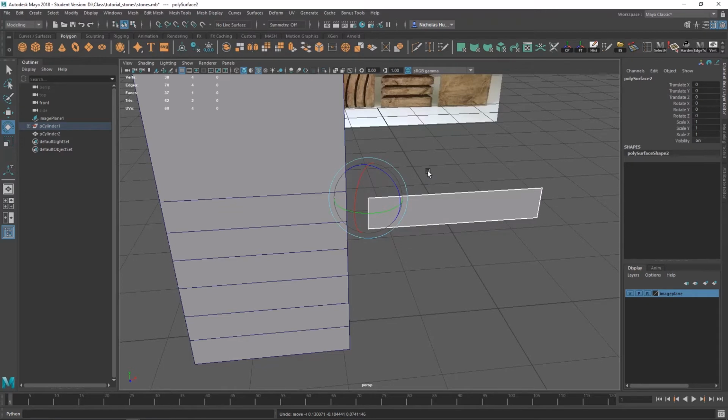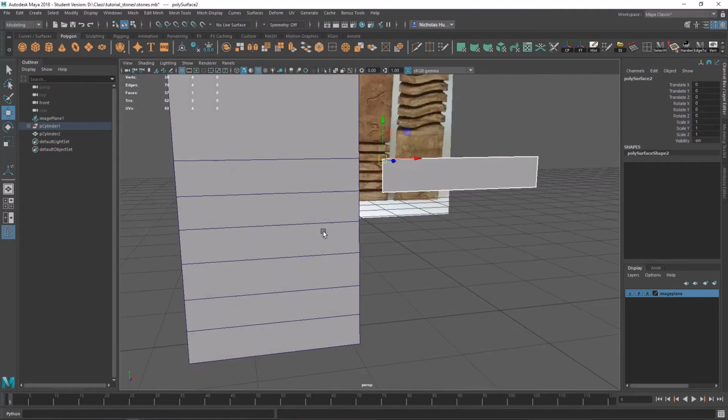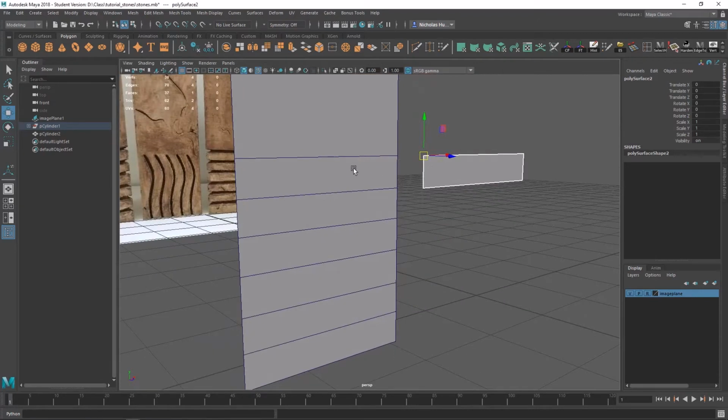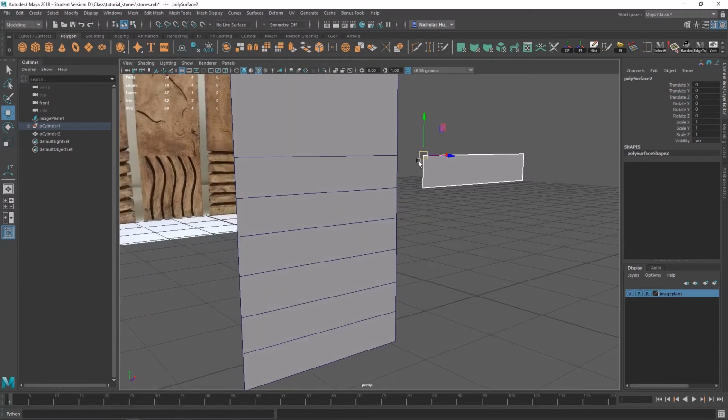I'm going to Control Z that. Going to go back to W, and we know that this is the same width as this because this is an exact copy of that. So now we're going to move this down to this edge line by pressing the little box here. Just click and hold, or I think we need to hold down V first. Hold down V as in Victor, and then left click this little circle thing, and it'll want to snap around. So snap it to right there.